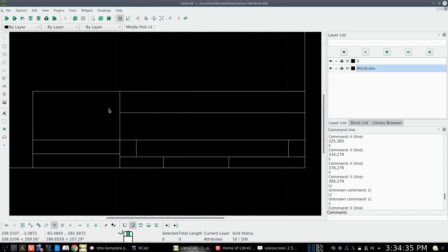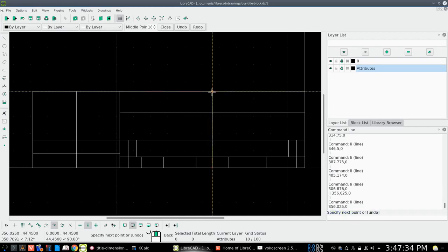Okay, right click to get rid of that. Let's put some center lines in there so that we know where center are on these things. You remember the border here, the bottom of our line is 410 long. So we know that when we're putting our line in, as long as we get the first line here, we can find center. And there is our center line there. Okay, we've got all of our center lines in there. Now we can shrink that back down.